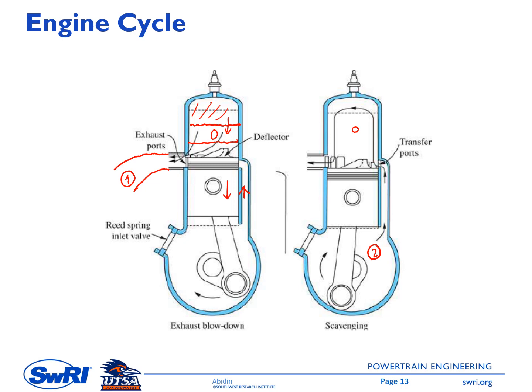So there will be a flow of this mixture from the crankcase to this combustion chamber. And then you can see also here a special feature of this piston. This is the feature of the piston, so that the fresh mixture is deflected up toward the cylinder head, rather than it just going to the left directly. The goal of this flow deflection is to maximize the scavenging process.